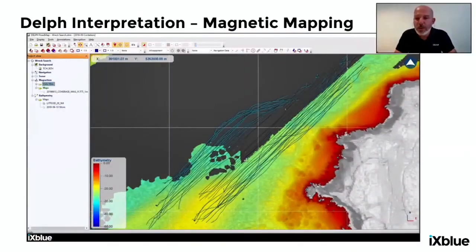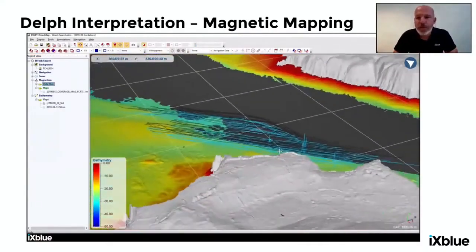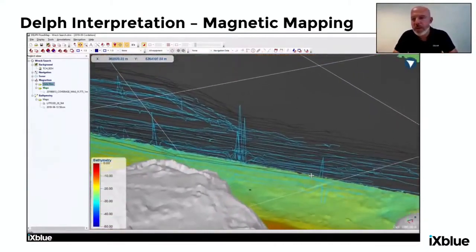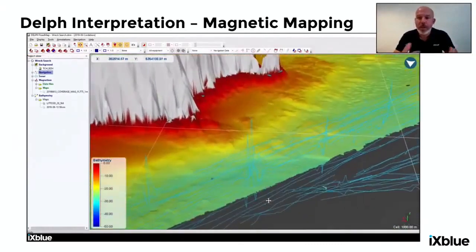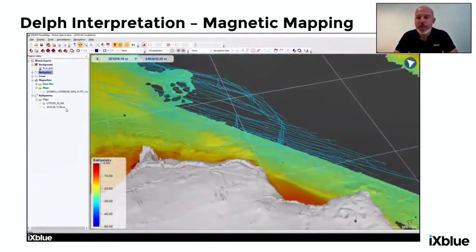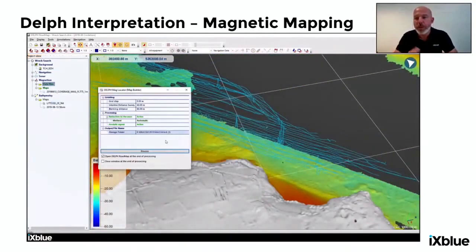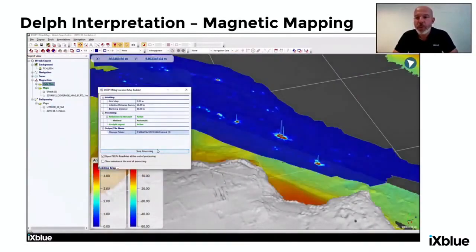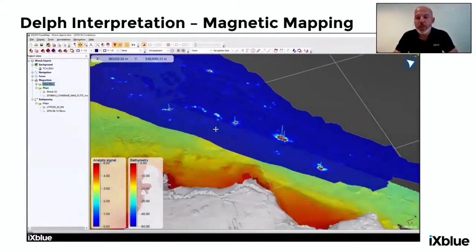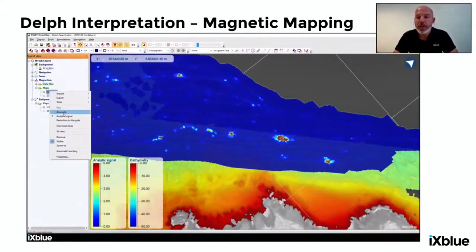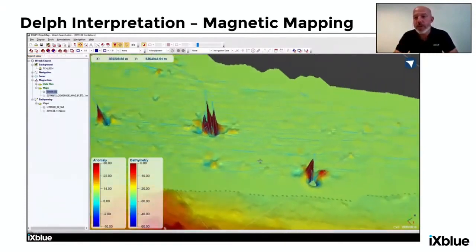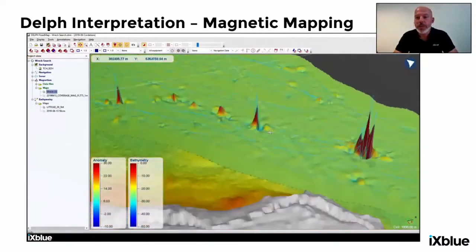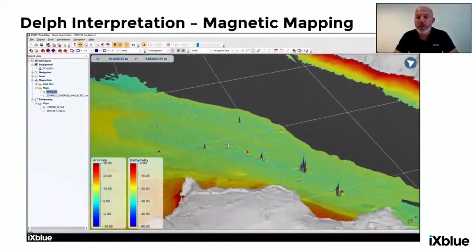You will see in this video that we have, again, the same mapping software integrating more sensors. We can see the magnetic data first being plotted like a wiggle vector line. We can see the track plot, and we can see the anomaly as a vertical vector line; we use the vertical dimension for that. Very quickly, we can do the filtering and the mapping of the magnetic anomalies, magnetic anomaly gradient, and so on, creating different surfaces that will help to locate all the potential hazards in the survey field.